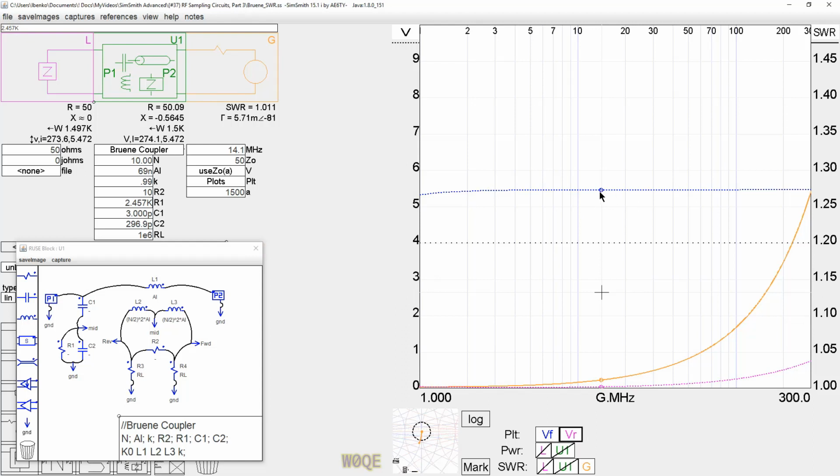That with a 50 ohm load, we see a pretty flat frequency response down to a little below 2 megahertz where it starts to roll off. That's due to an inadequate amount of inductance in this circuit. However, as I add more inductance, I start to have other problems. So it's always a trade-off. And this circuit is pretty broadbanded as it is.